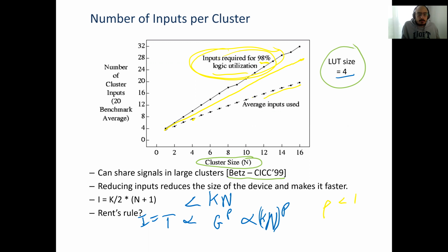So in the end, this is not an unreasonable way to choose how many inputs there are. But there's another way you can do it, which is basically you just change the number of inputs per logic block for every single size and see what's the minimum area solution, like what chip is the most efficient. And that chip might only hit 96% or 95% logic utilization on average.